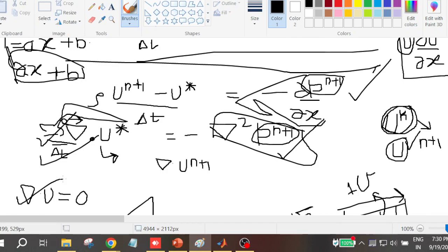I have one more doubt, a few doubts actually. There are properties for a numerical scheme: conservativeness, boundedness, and transportiveness. In that there is a Peclet number, which is the ratio of convection to diffusion.